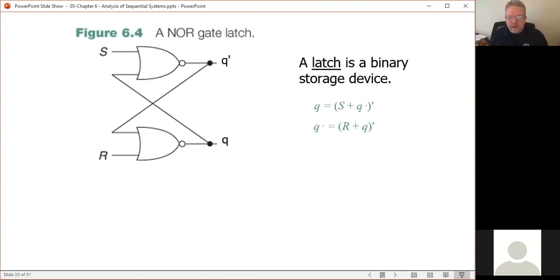The way that you make an RS flip-flop is you take a logic gate that you're already familiar with, which is a NOR gate. And like we talked a little bit about last time, you have this feedback where you feed back the output of one into the input of the other, and you do the same thing over here. Here's our two inputs, set and reset, and our output is Q. And this one turns out to be always opposite of what this one is over here. So we just call it Q prime because it's always opposite of that.